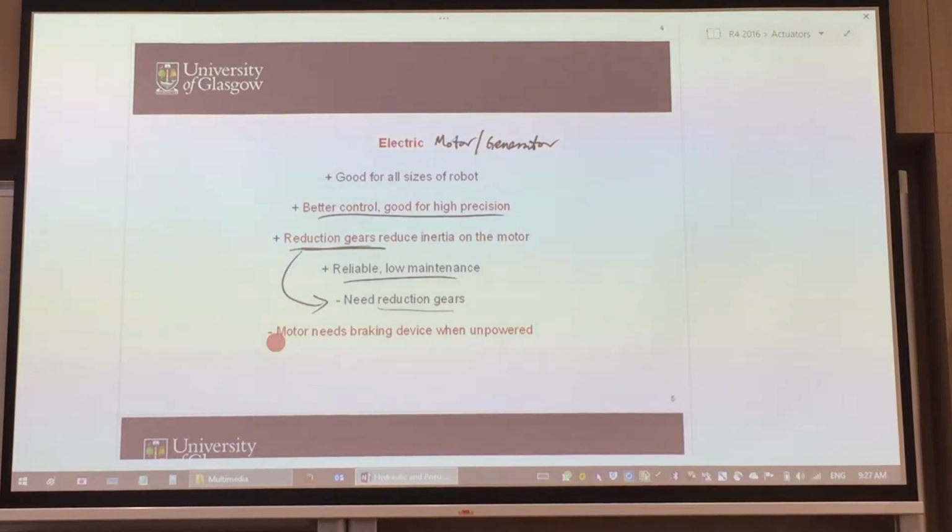So this is considered a disadvantage because a lot of times when you want to actuate something, you also need to come to a stop and stand still, let it stay there before the next actuation. Imagine if the load continues to apply on it and you couldn't come to a standstill, then it's actually hard to do your work.